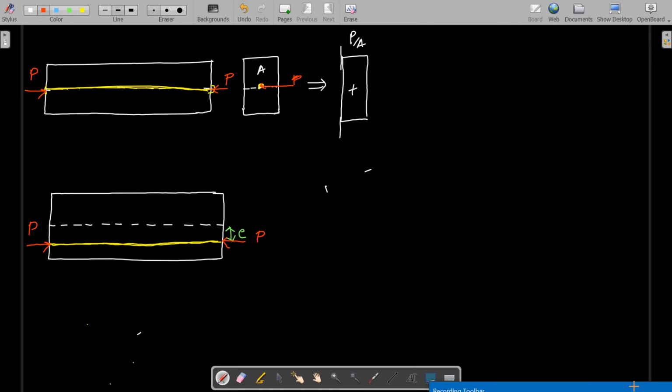If we draw the cross-section here, the section is like this. The neutral axis is here, and the pre-stressing tendons are placed over here, with an eccentricity E like this. There is also a UDL acting at the top. We will represent this UDL like this. We will use the linear elastic theory and analyze it separately. These are the stresses produced.